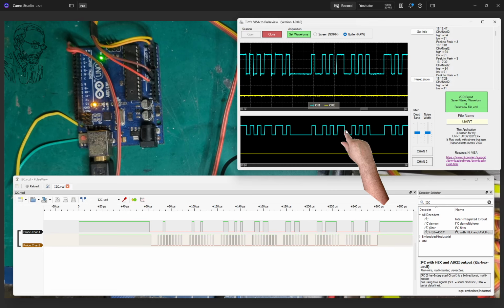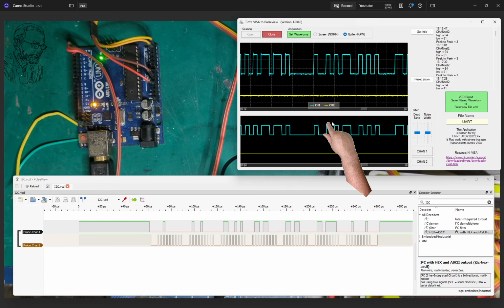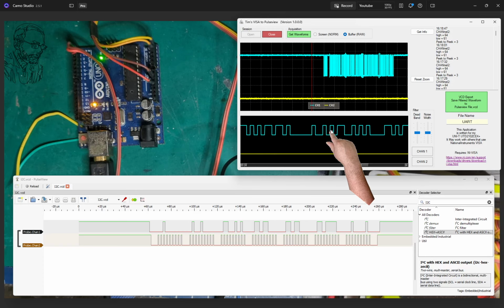And that's the thing with UART, you can actually transmit and receive at the same time, because you've got 2 serial lines. That's what I was trying to explain before, that these are 2 actual serial lines, but they're going in opposite directions. And the pulses are actually converted to digits using a time gate. You have a time gate between the pulses, and it works out whether it's high or low depending on the time it has been received. I hope that made sense.